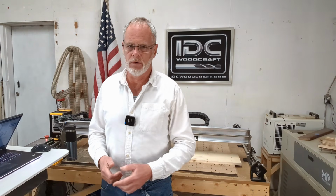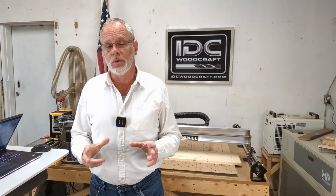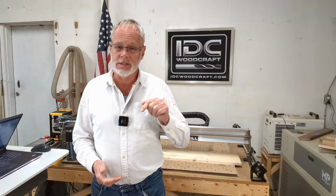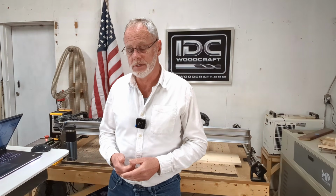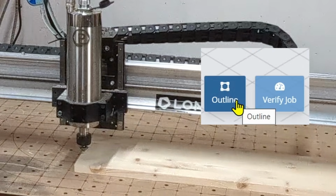Now we want to do the outline. So you want to make sure your router bit is not going to run off your material or hit a clamp. And this is the nice aspect of outline. What outline will do is it'll find the furthest most points of your G-code, and it's simply going to move your CNC router around those furthest most points. So when I click this outline mode, the router is going to move around.